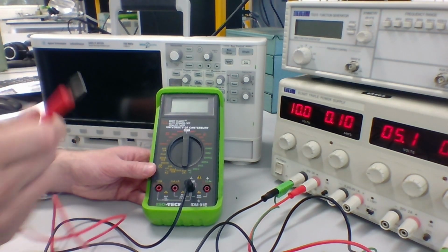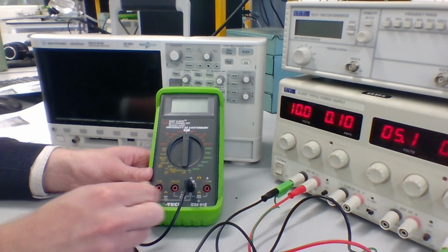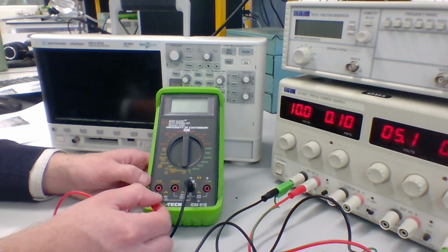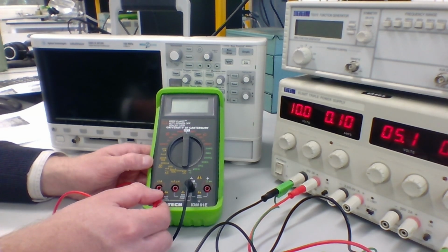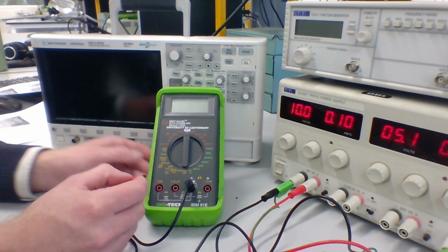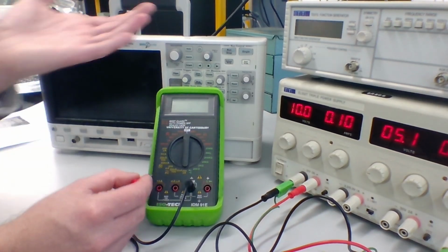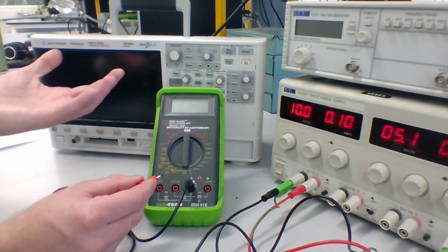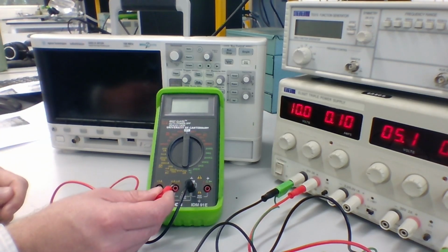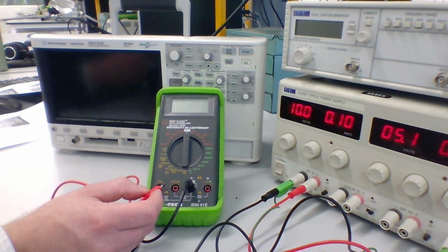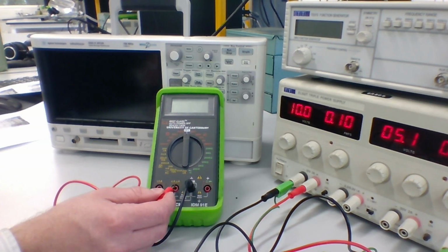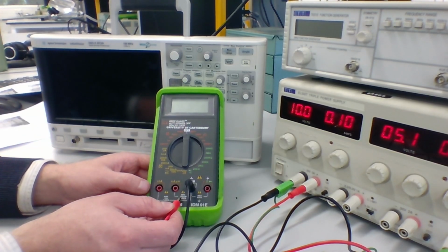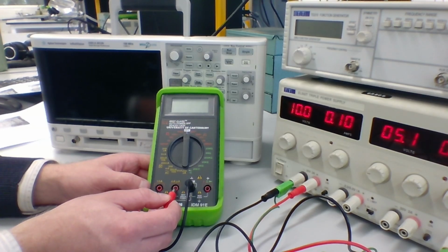So what I'm going to do is connect this into one of these 2 current ports here. There are 2 here, both have a different sensitivity and different fuse on them. We're expecting to measure a reasonably small current here. We've got 10 volts, 4.7 kilo ohms in this case, or whatever resistance you have in your case. So we don't expect to be measuring a high current, so I'm going to use the port labeled as milliamps and microamps. You'll note this multimeter has a 250 milliamp fuse on that port.